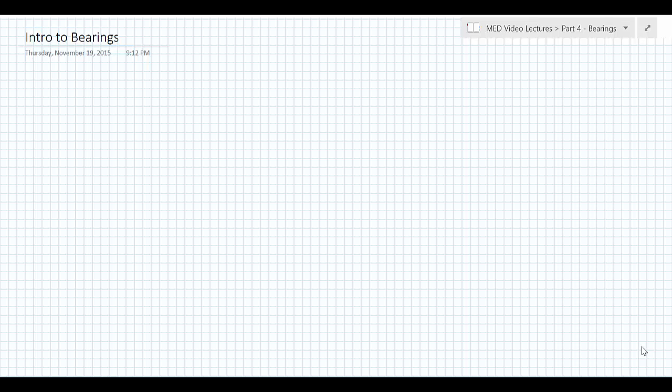Welcome back. In this video, we're going to introduce our discussion of bearings and how we pick bearings based on the rated load and their rated life. Bearings are a little bit different of a component than other things we've looked at, like shafts and gears, in that we aren't going to look for a factor of safety against fatigue wear. Instead, we're going to estimate a probability or a reliability that our part will continue to function. So this is a stochastic approach, a probabilistic approach.